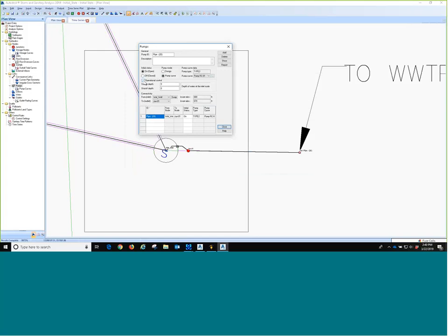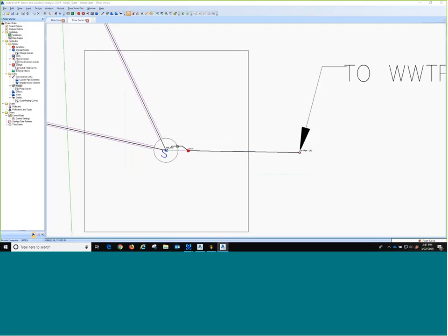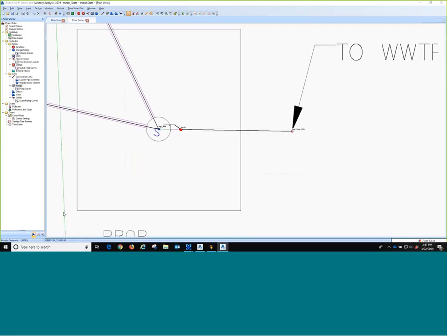And then I'm going to set this up as well and tell it I want to start up at 8 feet of depth in my wet well, and then I'll turn off when my water level reaches 2 feet of depth. Okay, so let's see what happens with that. Give it another run. And now let's look at the results in the time series plot.